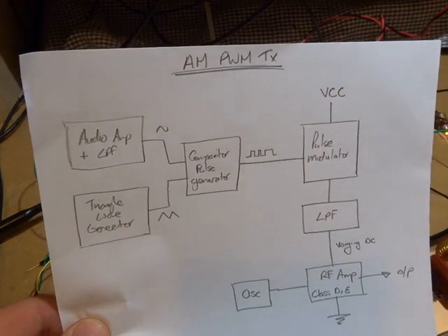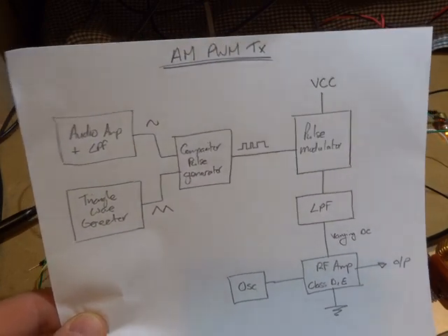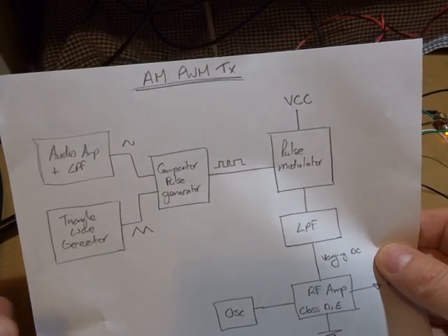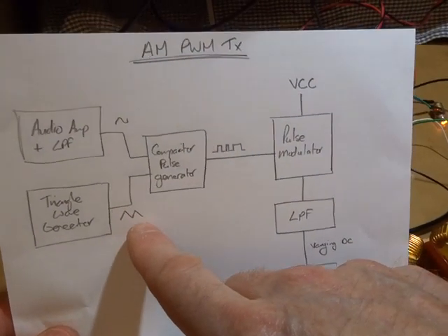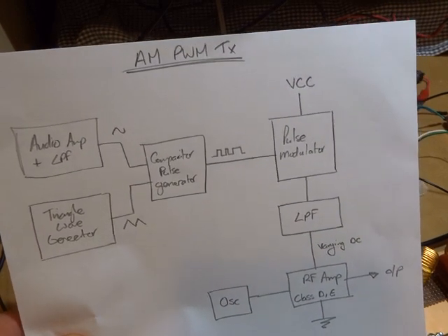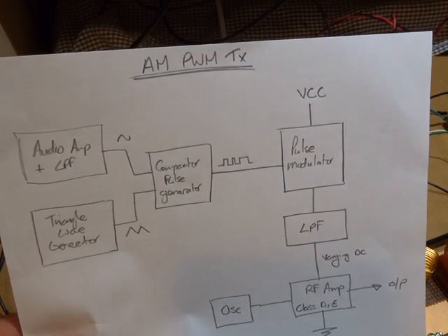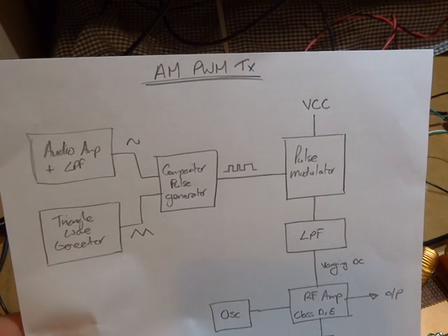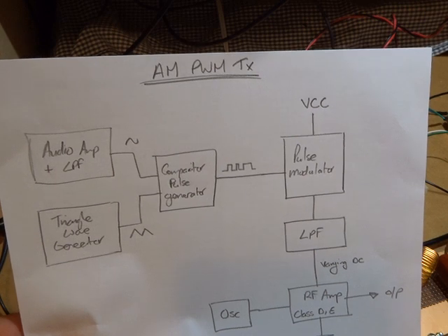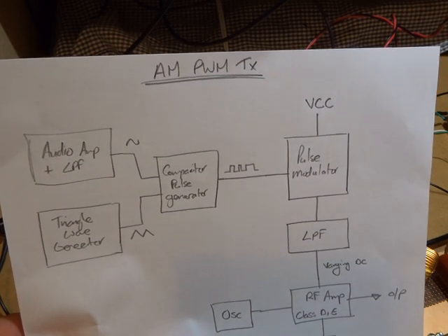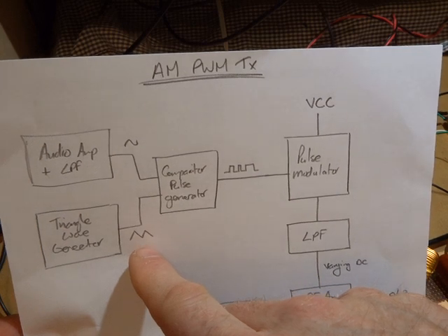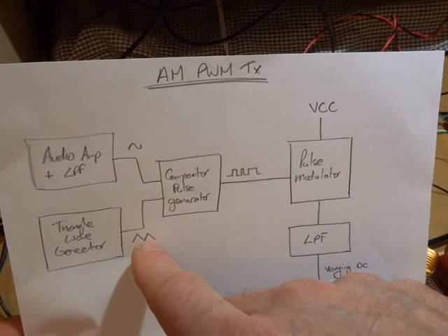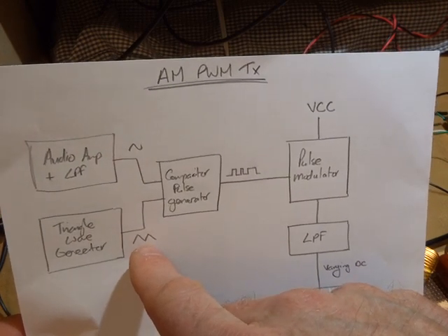Now, reading through some of the literature, and Stephen, like I say, had a good write-up on this, in terms of trying to select a frequency for this waveform down here, I understand that AM radio stations typically use a frequency between 50 and 100 kilohertz. So I elected to use 70 kilohertz, roughly in the middle of that. So that's what I'm using, 70 kilohertz.